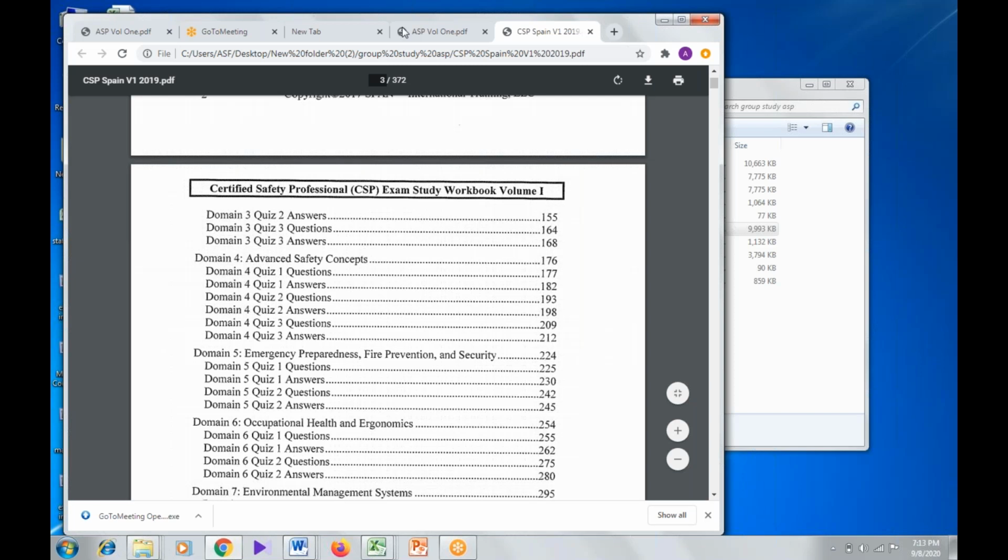But if it is less than 1,500, I think it will not be included for the OSHA PSM program or the environmental protection plan. So if it is more than 2,500, you should apply both measures, process safety management and environmental protection.